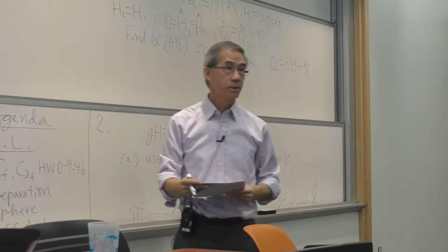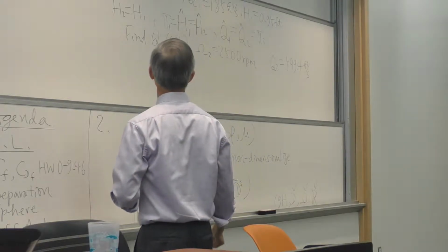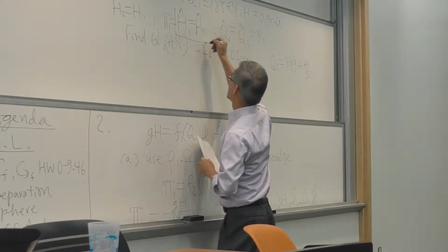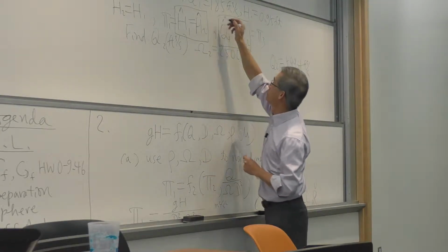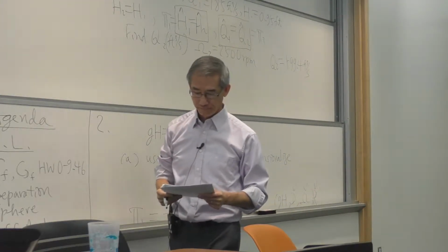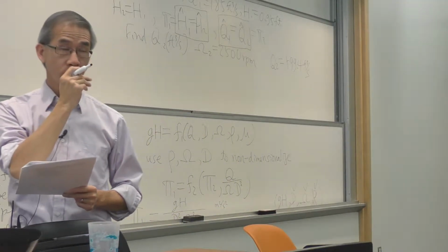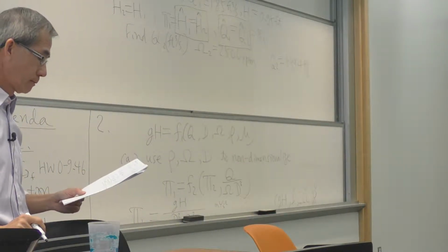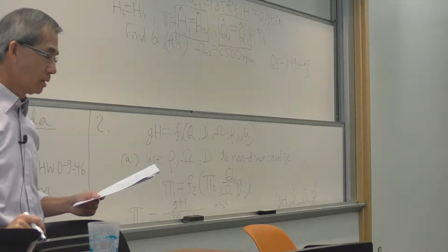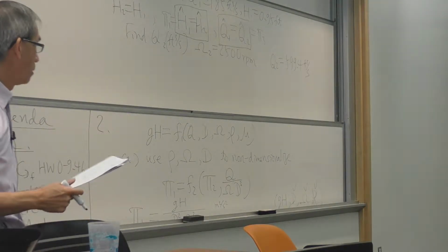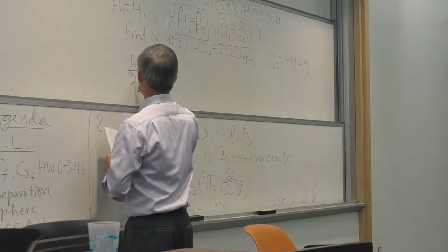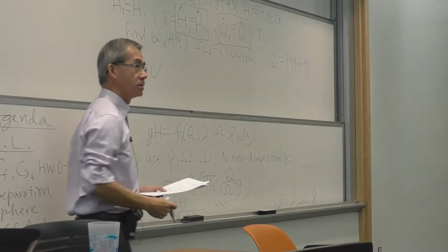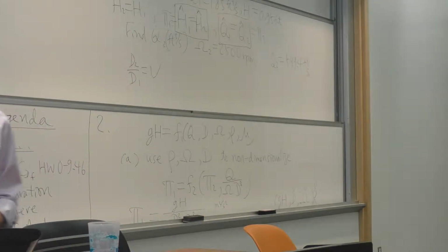And the way you approach this is to match dimensionless head, which is from part A, and dimensionless Q, which is given in part A. And when you do, the final answer will depend on D2 and D1, which is a ratio you can determine somehow. I won't tell you how, but when you work the problem, that will come out.